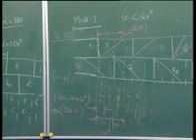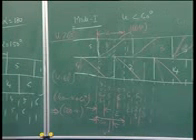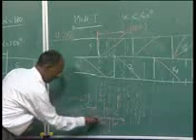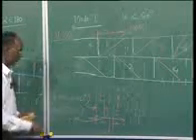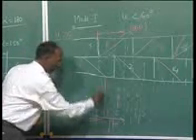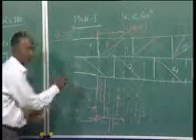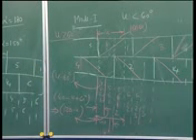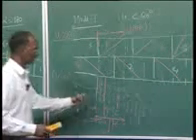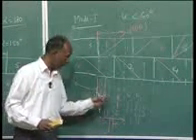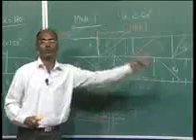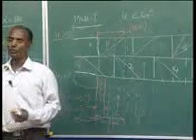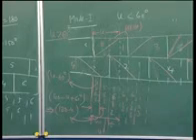So, in the 3-4 valve conduction mode, this period is your 120 minus U, and this period here is your U minus 60 degrees, and the pattern will follow, and this is symmetrical: 3, then 4, then 3, then 4, then 3 and so on and so forth. So, this is your mode 2 case, which is just going to happen.